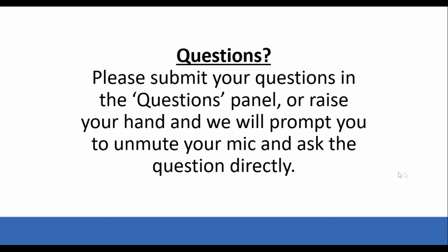Yeah, so good question, because obviously if we're working with powders, we want to make sure that we're not using fine powders. In the case of molecular sieve 13X, it comes already as, I want to say, 45 mesh, but generally all the powders I've sieved to be between, I think, 250 micrometers and 180 micrometers. With the monoliths, they're much larger, so we can generally go to much higher sizes. But with the powders, we do sieve them to between 250 and 180 micrometers, just so we don't have too much pressure drop in the system.